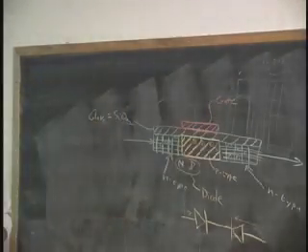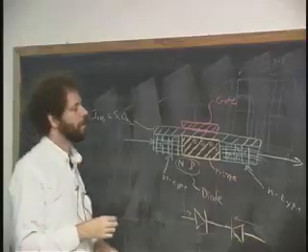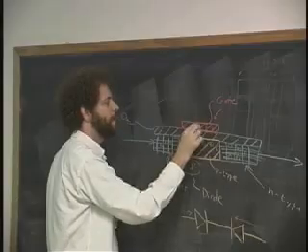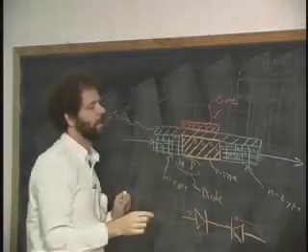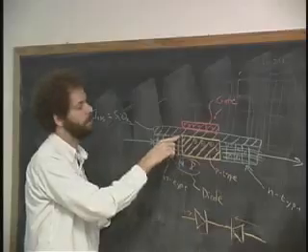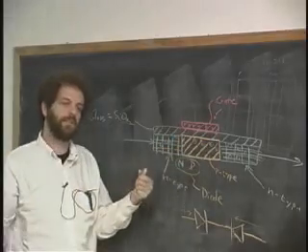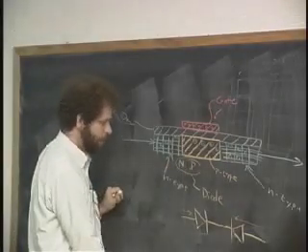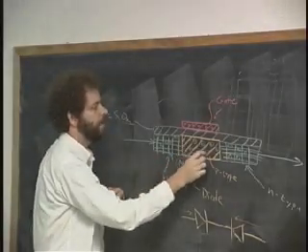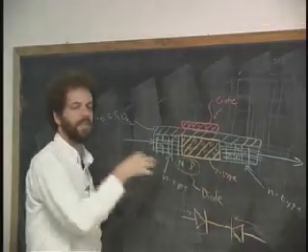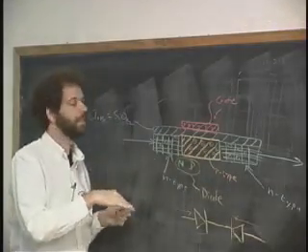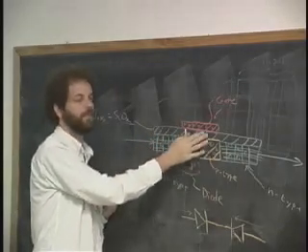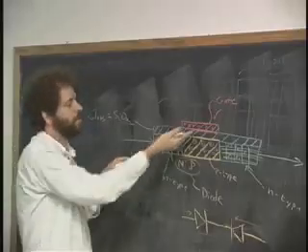And guess what happens? In the same way the capacitor worked, if I put a lot of positive charges into here, let's say I fill this up with positive charge, guess what gets attracted to the surface right over here? Because remember, positive and negative want to go towards each other. It turns out that there's a few negative charges floating around in here. Not many, but there's a few. P-type means there's a lot of pluses and a few minuses. But if I put positive charge on the gate, all the minuses drift up to the top because they all want to get close to this positive gate.